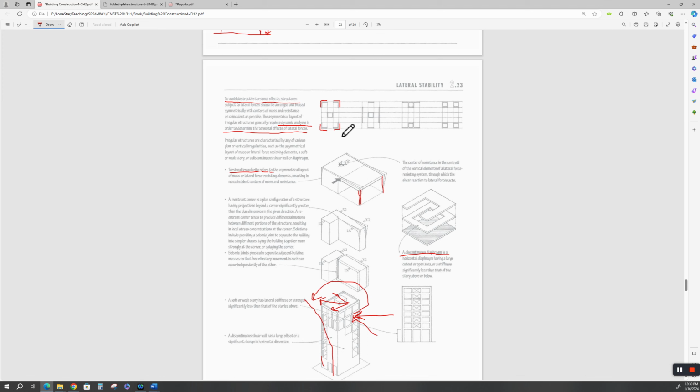So these represent shear walls. That's a shear column. You see that in a lot of structures where your elevators are. If all this framing was framed up in wood, like in some apartment complexes, your stairwells would be out of concrete and engineered so that they reduce shear.